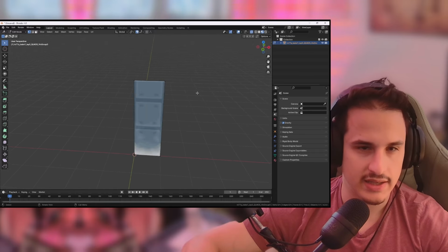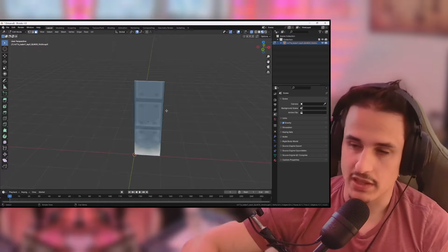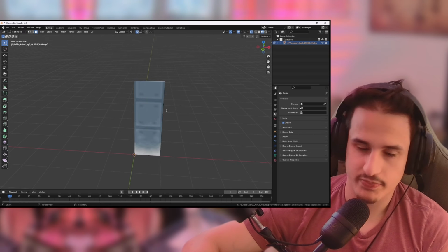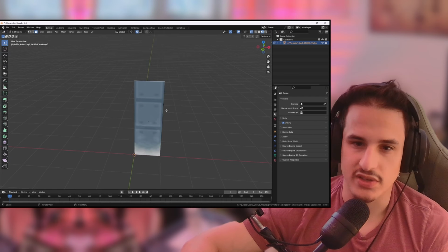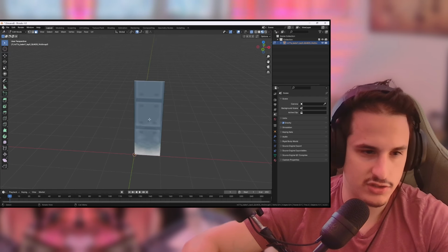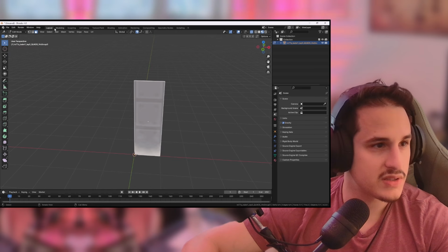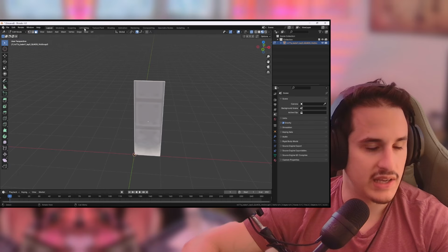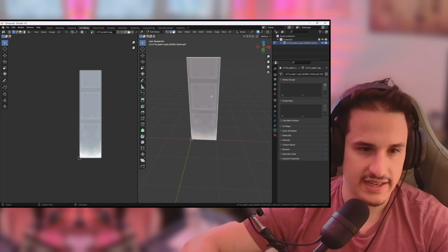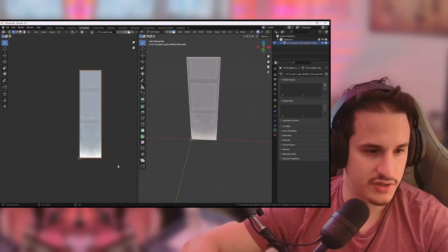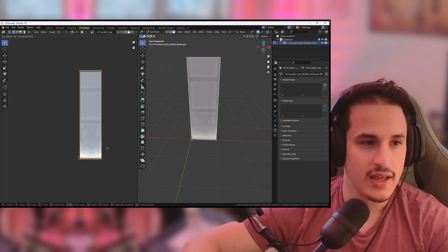Now, the caveat here is that sometimes your UVs might be messed up. And what I mean by UVs, if you're not familiar with that term, this means your X and your Y direction texture. U and V are just like the coordinate system for your textures. So you can always click on this and then go up here where it says Layout, Modeling, Sculpting, UV Editing, and click UV Editing. And you can see how this texture is assigned. So I can grab this and move it around, and you'll see how the texture actually moves around here.